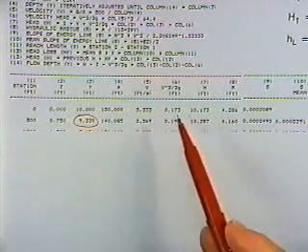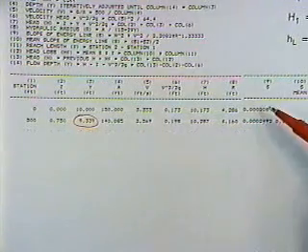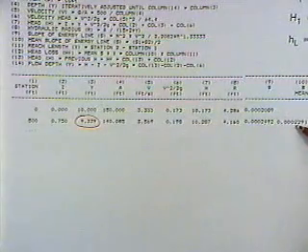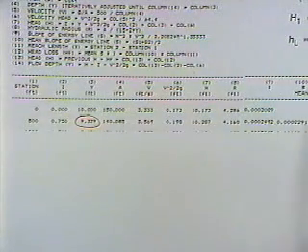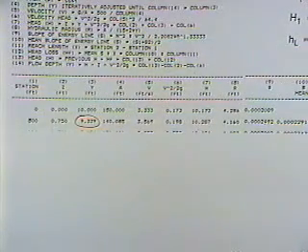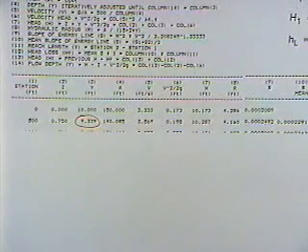I can compute the area, the velocity head, the total head, the hydraulic radius, the slope from Manning's equation, and then knowing the slope from Manning's equation at that section, and at that section, I can average those two together to get an average slope. Then I use that average slope and the distance between the two sections to get a head loss term. And then I know that if I take the total head at the previous location plus the head loss, I've got the head at this location.